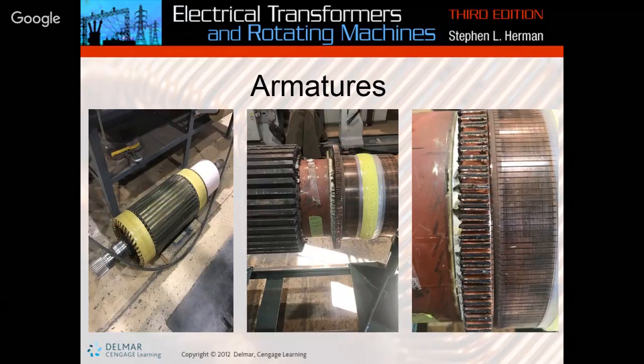All right, so here is an armature without the loops. That whole space right here is going to get filled completely with little thin strips of wire. Each one of those is going to be a nice packed, tight loop of wire, and it's going to come out to be the same height as these iron core slats. Once we get done with those wires, we take the end of each one. This coil is going to have a beginning and an end, and we're going to hook it in right here on one of these little slots inside of this commutator.